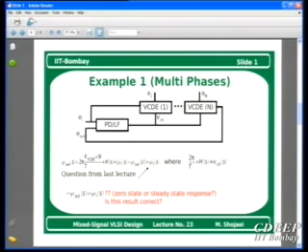You have a 1 degree change here, you get it at 0 time here. Then what does this do? Nothing. Exactly. This analysis is based on considering we get it in 0 time. Therefore, we don't have any phase shift, any phase difference, or any phase error at the input of the phase detector.